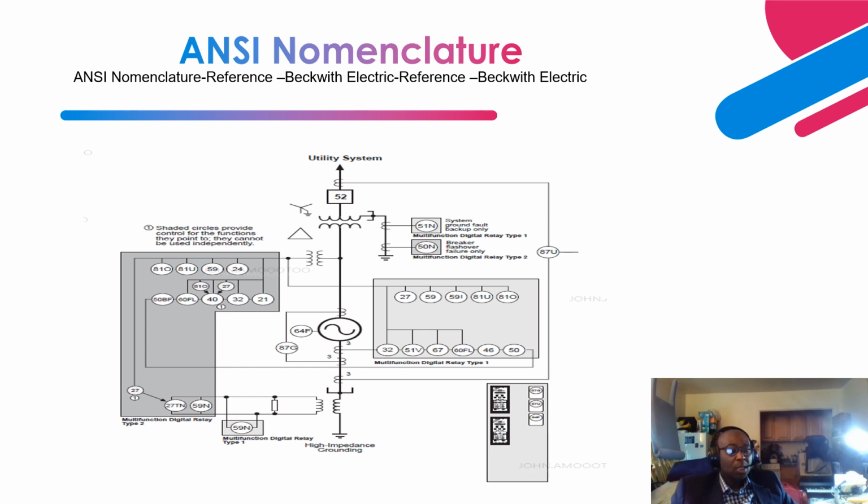Next is 27. 27 is an undervoltage relay. Let's say you have a heavily loaded generator, the voltage is going to go down, or inaccurate sensing of voltage. Then this is when this relay sets in and trips the required breakers.